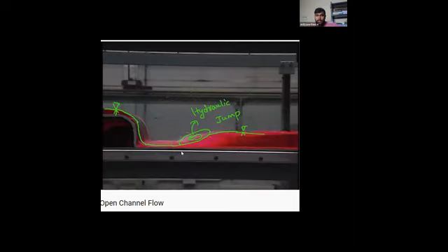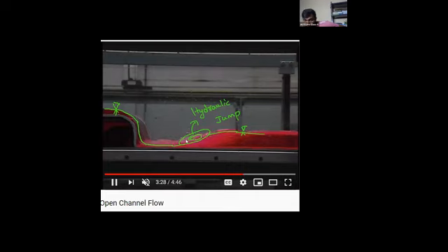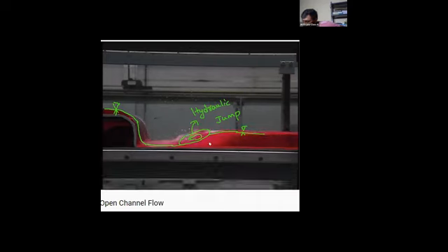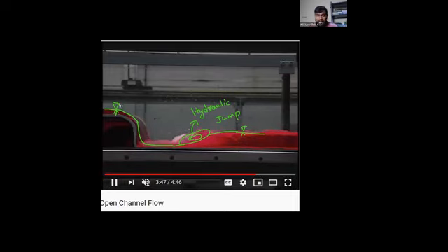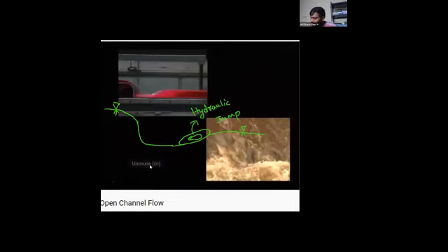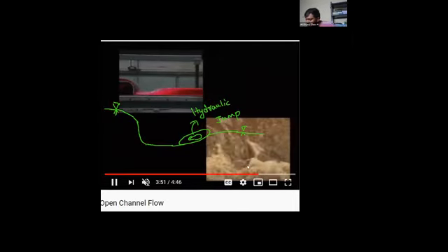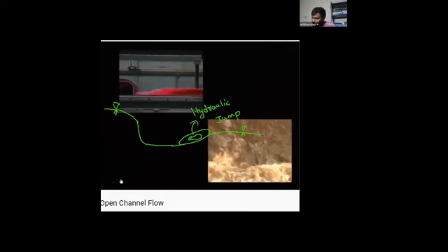Yes, you observe over here. You can see in this portion, you can observe the flow is passing in a reverse direction. It moves forward and backward, and it is creating some disturbance over here. Due to that disturbance, the energy is going to be dissipated. The energy is lost. That is the reason why the water will not rise to the same height, and it is not going to be exactly similar to here. Please observe.